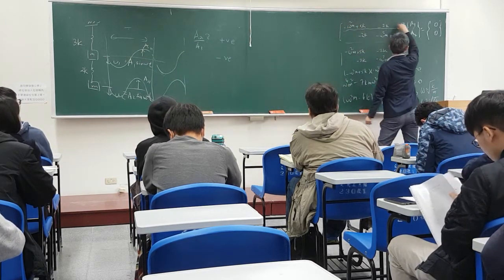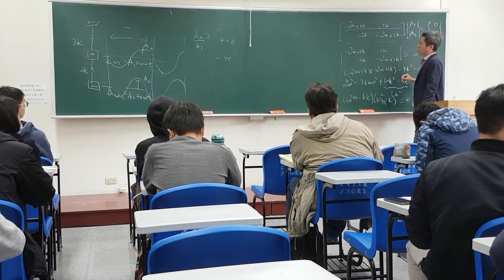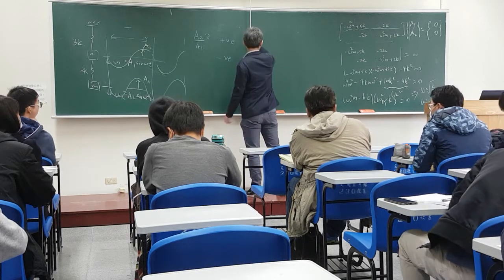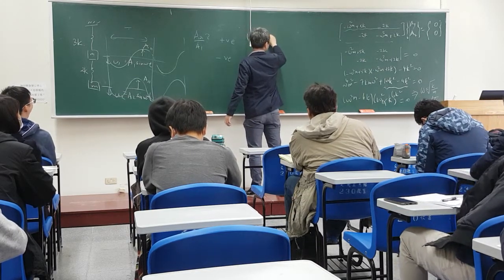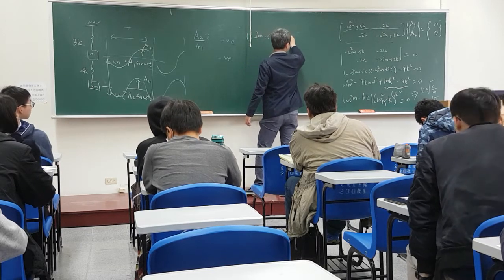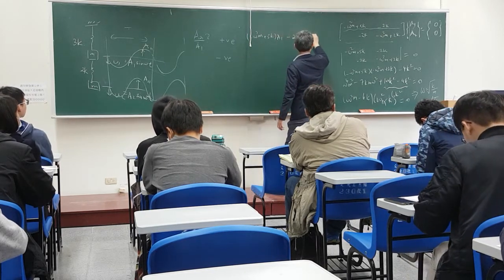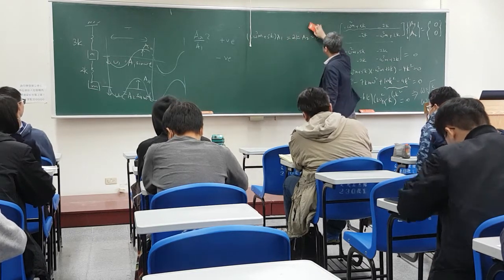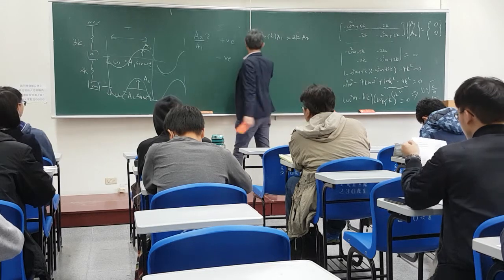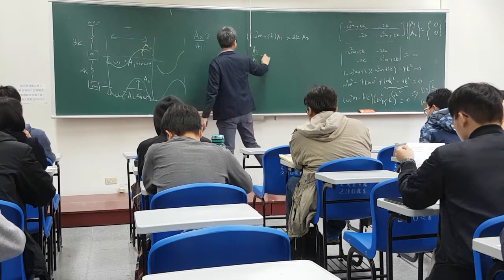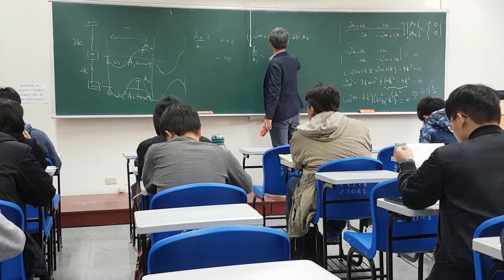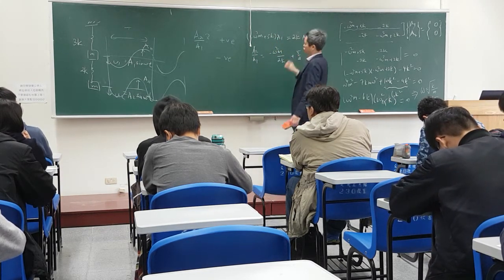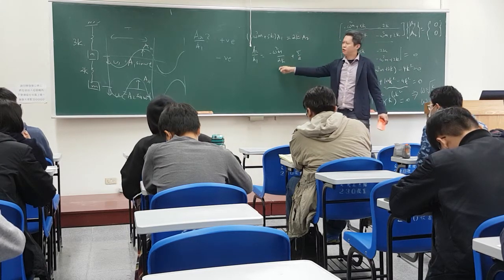You can take the first equation, okay? How to get the first equation? You take the first equation by writing out minus omega square m plus 5k times A1 minus 2k A2. Okay? So you move this to the other side, and this one becomes equal. Now you can find the amplitude ratio A2 over A1 is then going to be minus omega square m divided by 2k plus 5 over 2. Okay? So now this is your amplitude ratio.